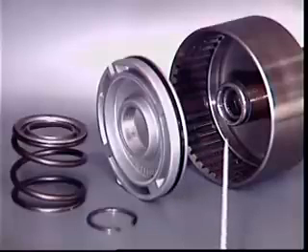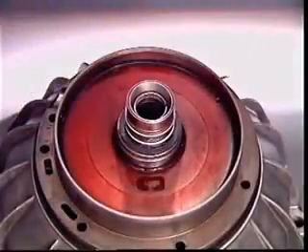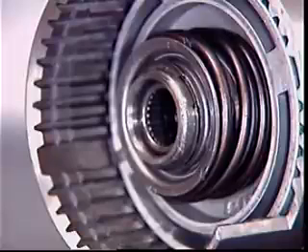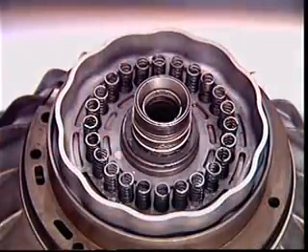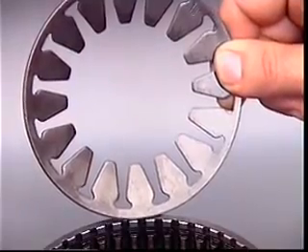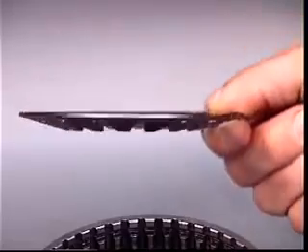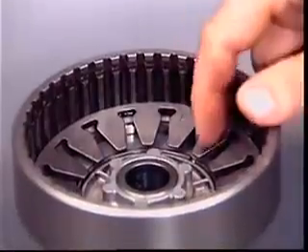It moves in a short cylinder in a clutch drum, or in a cylinder machined in the casing. Release can be effected by one large coil spring or by a pack containing many small springs. When a diaphragm spring is used, it gives extra leverage to increase the apply force as well as providing the release force.